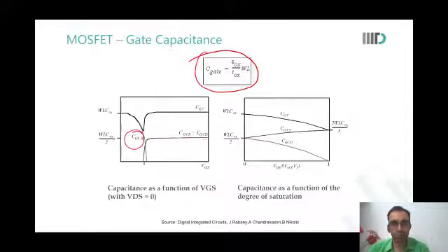Okay, sir. After this, nothing is told about saturation. That is the second graph, the graph on the right side. So if we increase this VDS, then VGS and VGD both will become 2/3 in the first graph? No, due to pinch off, the drain will have no influence. Therefore, the gate to drain capacitance goes towards 0, and the gate to source will increase to 2/3.